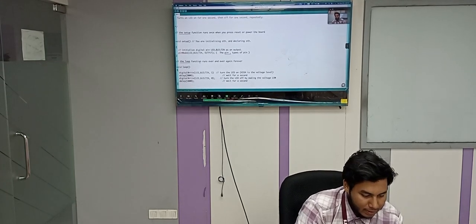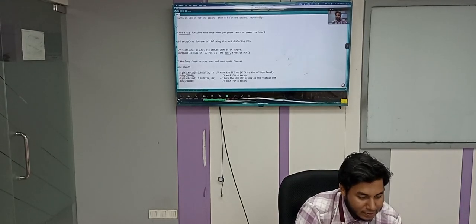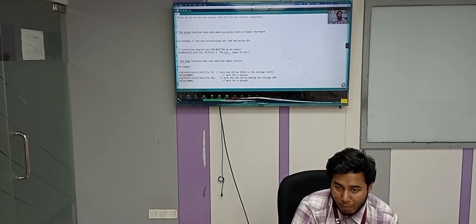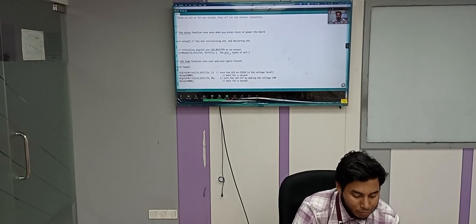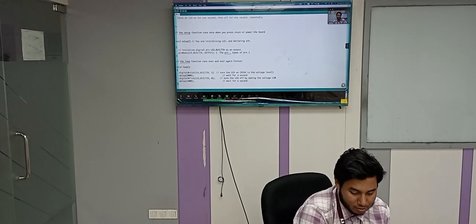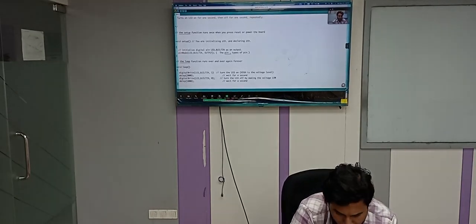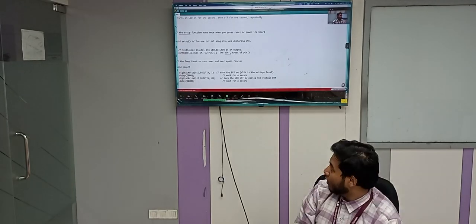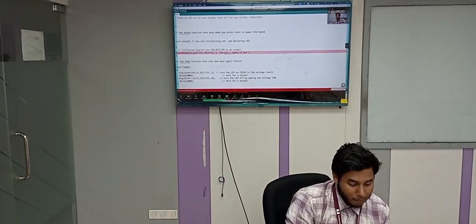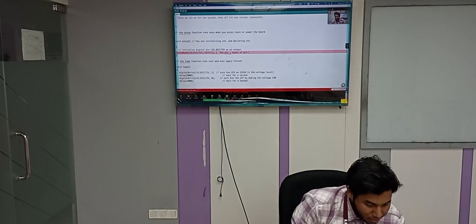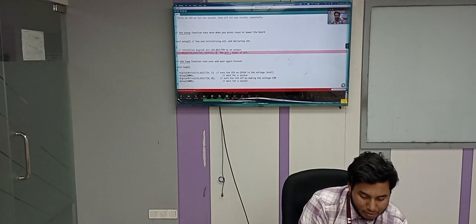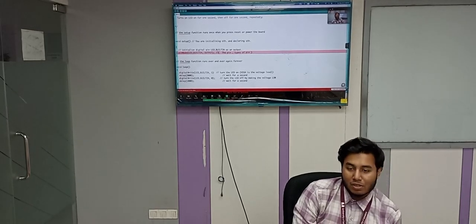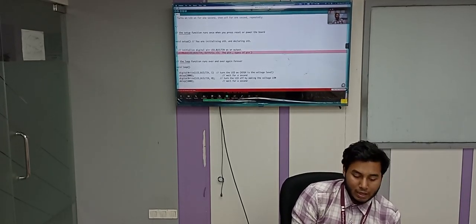Yeah, fine. And if I check or verify this, because I'm not uploading this code, it will obviously figure out a problem. See how this problem has been shown in the Arduino IDE. It's just compiling the sketch. There's a problem. See, pinMode was not declared. If I did not put any double slash, it will be considered code.